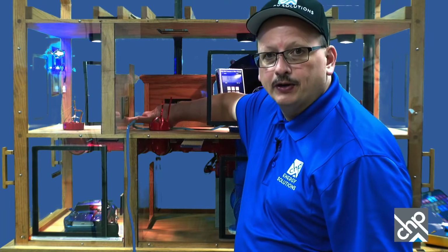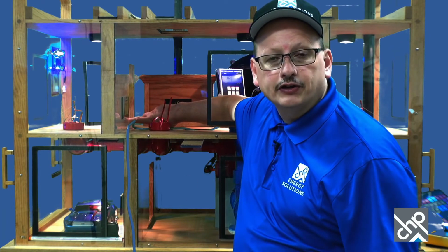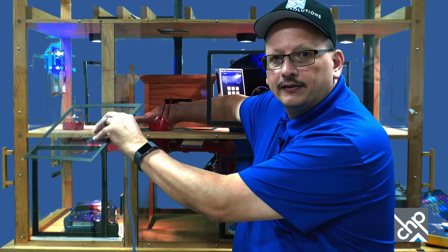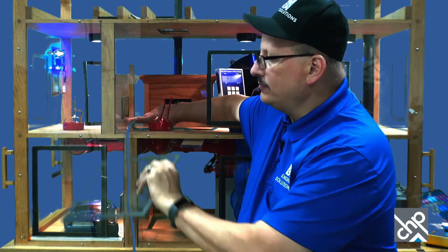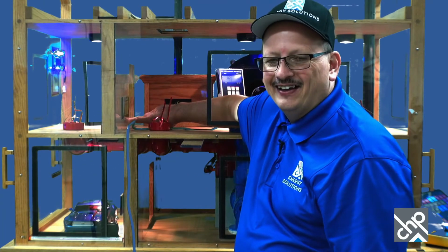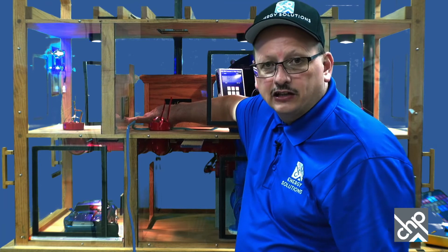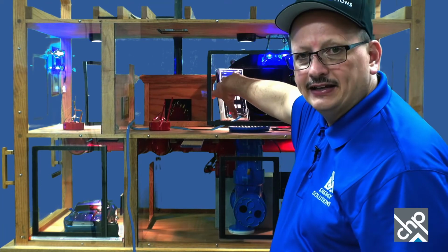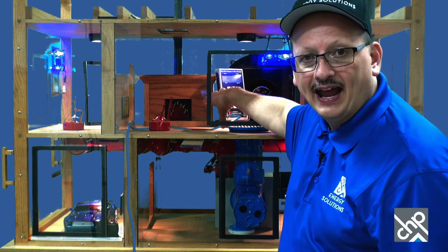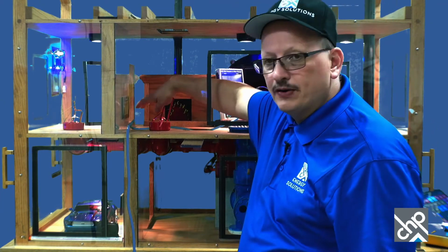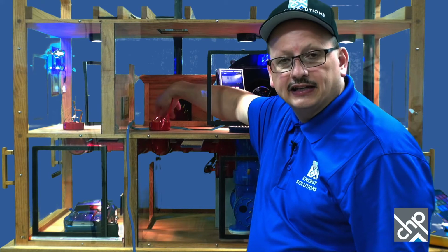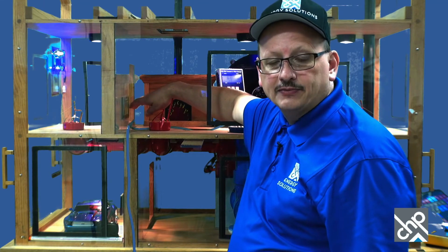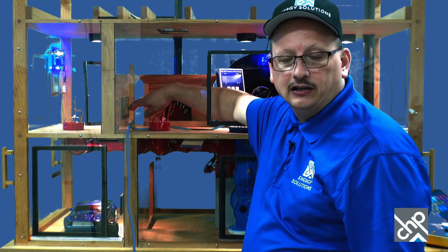If it pulls smoke under the door, then that means you want to open the door. Like for this master bathroom over here, when the door is closed, if it's pulling smoke under the door, that means it's trying to suck air from my CAZ. If I puff smoke at the bottom of the door and it doesn't get pulled under, then that tells me I want to leave that closed.